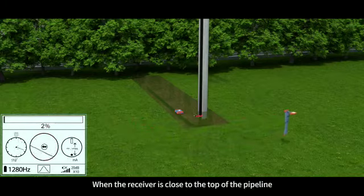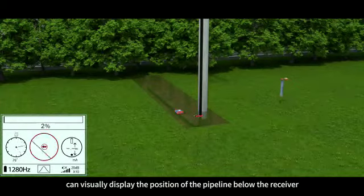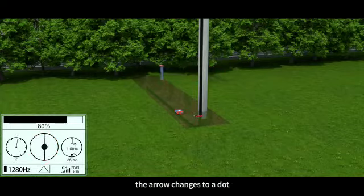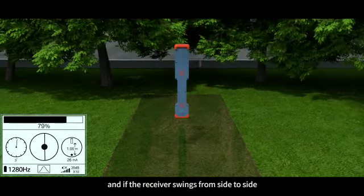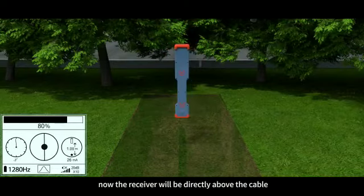When the receiver is close to the top of the pipeline, the compass in the center of the screen can visually display the position of the pipeline below the receiver, and the arrow in the center will point to the cable. When the receiver is directly above the pipeline, the arrow changes to a dot, allowing rapid checking of the pipeline. Observe the direction of the arrow. When the arrow becomes a dot and the receiver swings from side to side, the arrow will reverse. Now the receiver is directly above the cable.